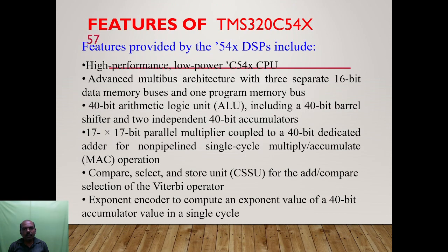Features of the TMS320C54X series: high performance, low power C54 series; advanced multibus architecture with 3 separate 16-bit data memory buses and 1 program memory bus; 40-bit ALU including a 40-bit parallel shifter and 2 independent 40-bit accumulators; 17-bit parallel multiplier coupled to a 40-bit dedicated adder for non-pipeline single cycle multiply-accumulate operations; compare, select and store unit for the add, compare, select of the Viterbi operator; exponent encoder to compute the exponent value of a 40-bit accumulator value in a single cycle;